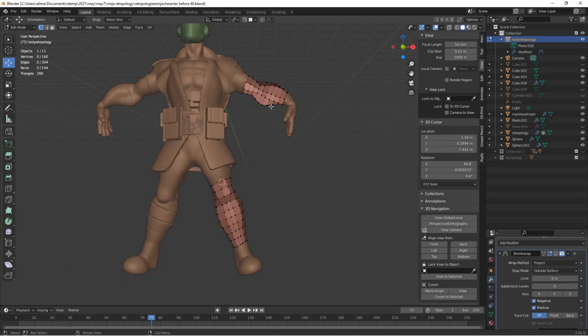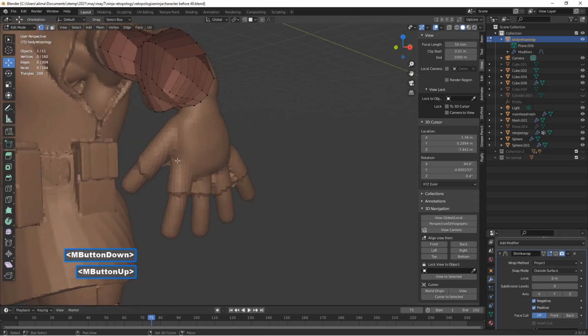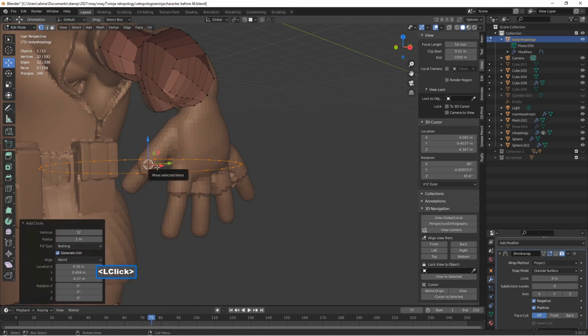Okay, here in edit mode, I'm going to go over the hand, hold shift, press B. This lets us draw a box. As soon as I let go, we're going to zoom into the hand. There we go. We'll hold the mouse button, rotate. We'll hold shift, then right click on the hand here. Be careful of being too close up to here. We're going to hold shift, press A, select circle, go to the left, change this to 8. Hopefully you're familiar with this by now.